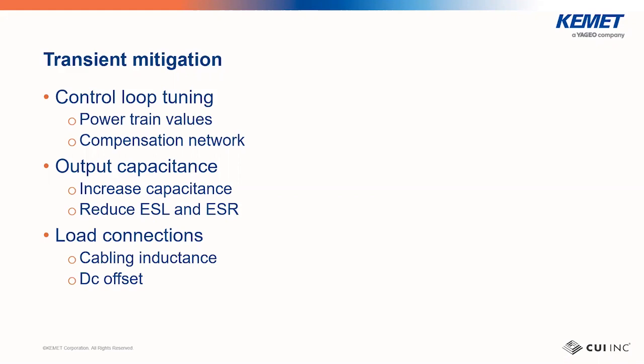For the user of a power supply, as opposed to the designer, we have limited options. Essentially, the only option we have is to increase the capacitance. ESR and ESL should also be minimized so that they don't factor in.